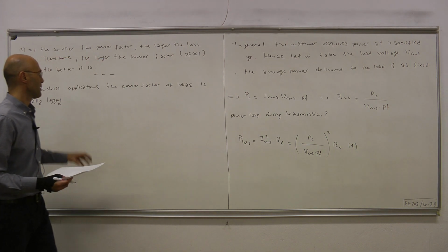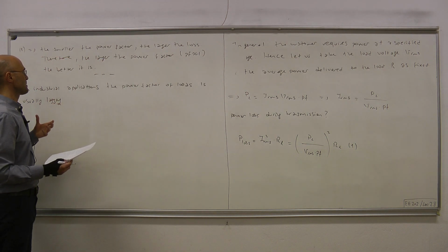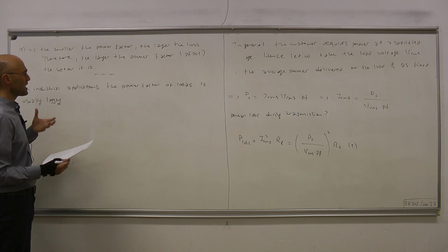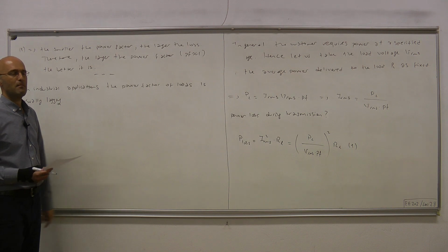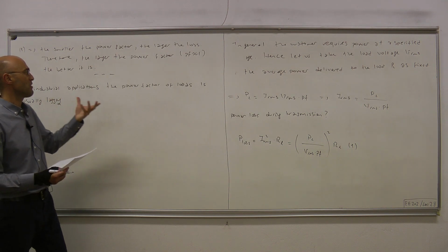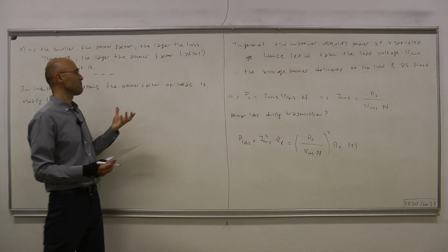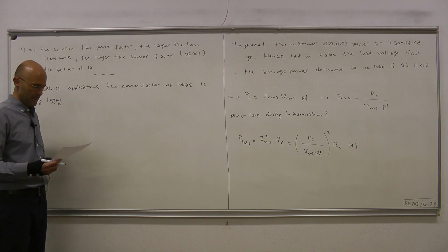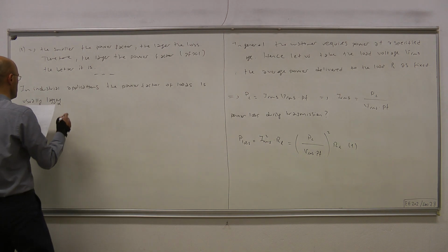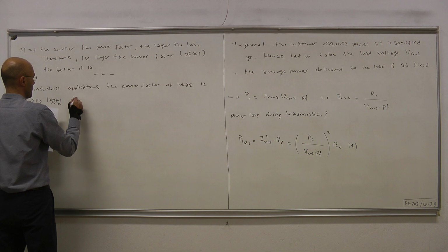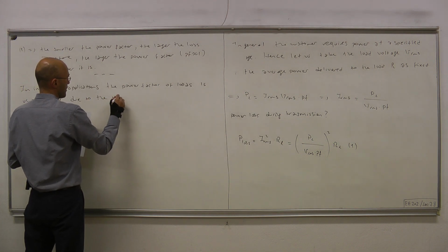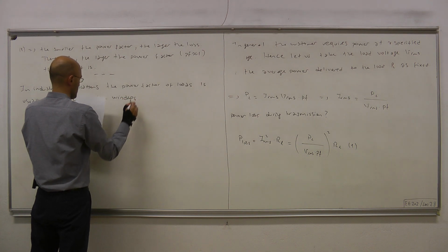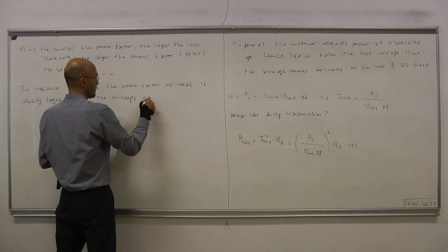So the inductive effects will be dominating the capacitive effects, and if you do nothing about it, the power factor of loads will be lagging due to the windings of the electric motors.